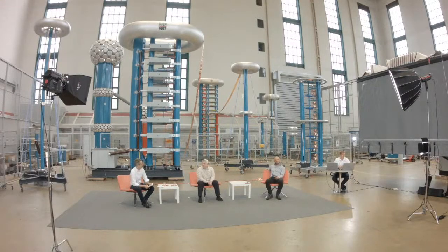Okay, a cable question. Does the contaminant in insulation affect the PD value or lifetime of the cable? That's the question to Berlin. Lifetime depends on the size of the particle and the field enhancement. So we call it electrical aging. That can last for decades before it leads to inception of partial discharge.